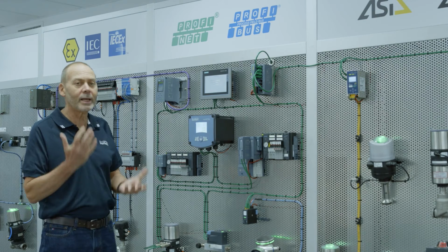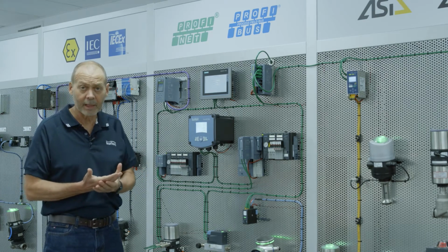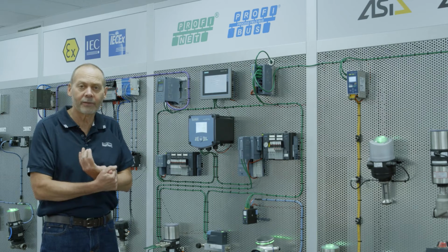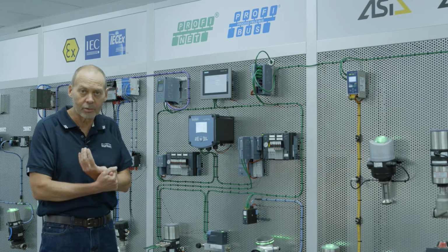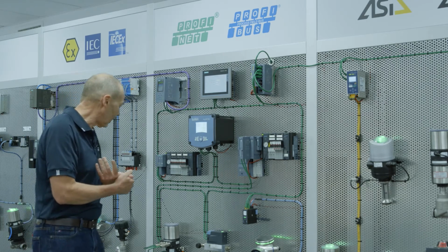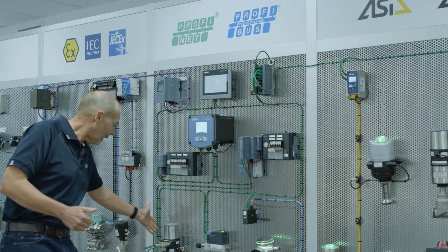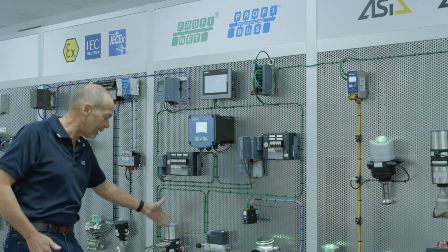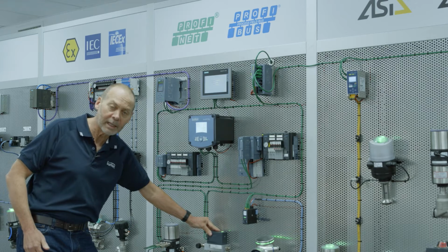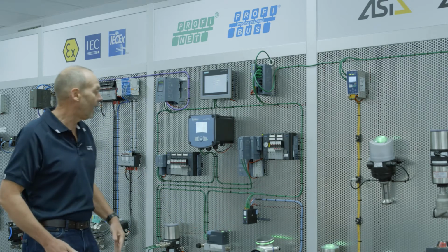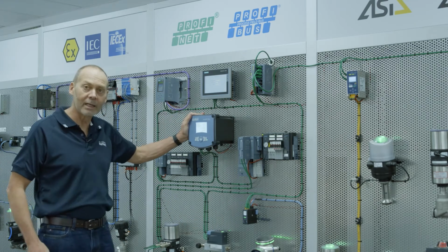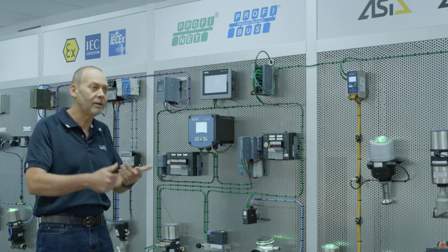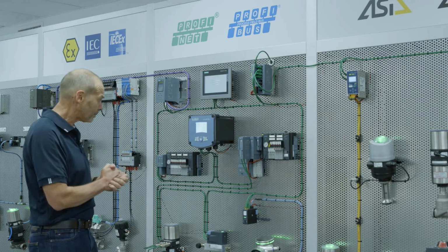So there are a number of ways that we can take Ethernet to the field, and there are three main ways you really have to consider. One is having devices that connect directly to Ethernet. As an example here, we've got a modulating control valve connected directly to the PROFINET. We've got a mass flow meter connected directly to the PROFINET, and we've got our Bürkert multi-cell connected directly to PROFINET, which may be taking in things like pH, conductivity, turbidity, etc.